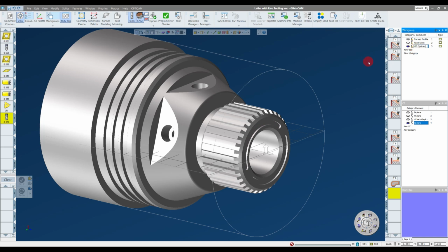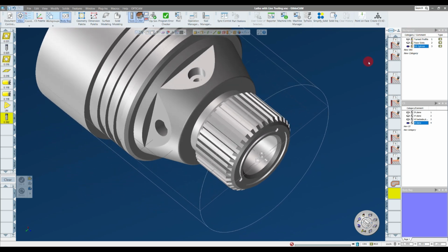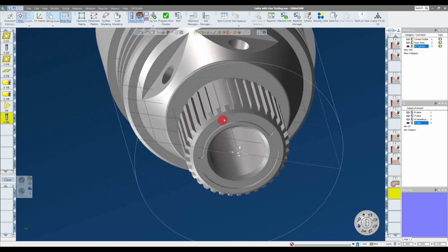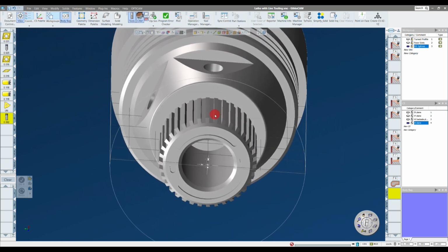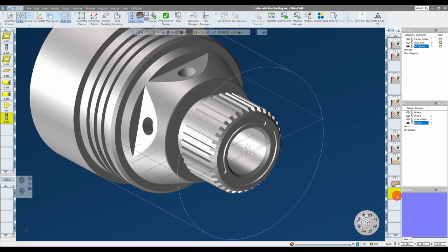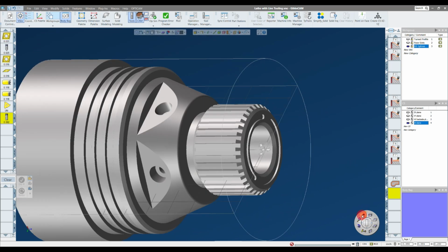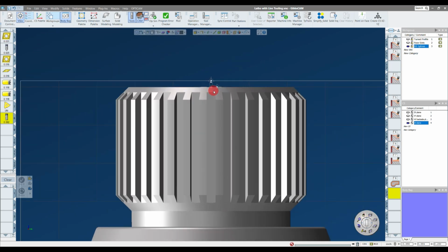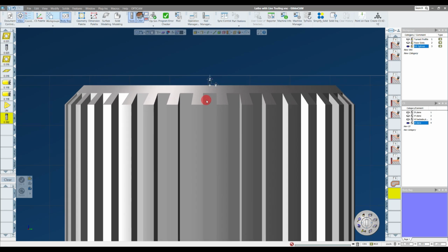How about that? Okay. Now, I only need to machine one of these splines, and I can rotate and duplicate it around. So if I go to my home view, it gives me a bit of a normal view. So I'm going to pull the geometry from this center spline. If you pull an offset geometry, it's not going to go very well. So you want to make sure you pull the geometry from this center spline.